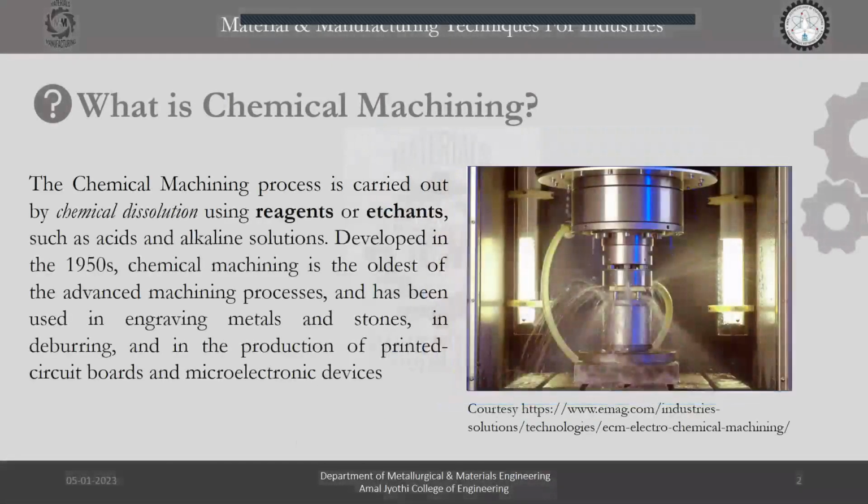Now, chemical machining is a material removal process for the production of desired shapes and dimensions. It is done by a selective or overall removal of material by a controlled chemical attack with acids or alkalis. The metal is slowly converted into a metallic salt by chemical reaction and is finally removed in this form. Areas from where the material is not to be removed are protected by an etching resistant material.